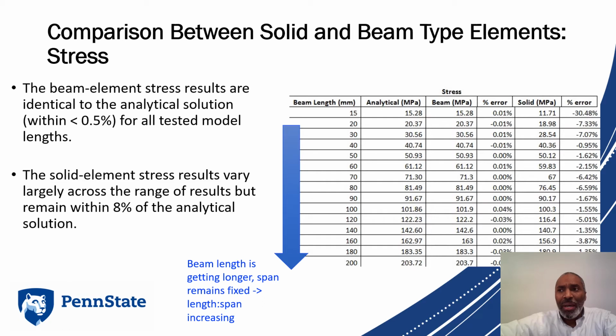And some will be a little bit higher, some might be a little bit lower, depending on where you actually sample that solution with respect to your beam. But if you were to integrate over some whole face, then the whole face would have to satisfy equilibrium, and the whole face would then probably be closer to the analytical solution than we have here. Well, as close as it could get, given that the solid solution is going to differ somewhat.